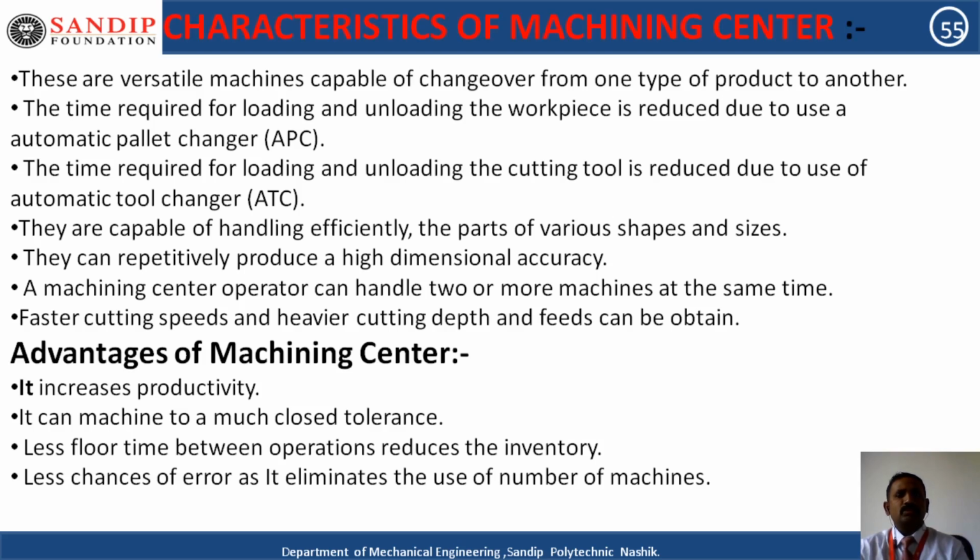Now, characteristics of the machining center. These are versatile machines capable of changeover from one type of product to another. The time required for loading and unloading of the workpiece is reduced due to the automatic pallet changer. Similarly, the time for loading and unloading the cutting tool is reduced due to the ATC, the automatic tool changer. These are two different functions, APC and ATC.